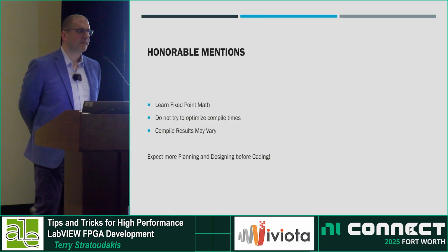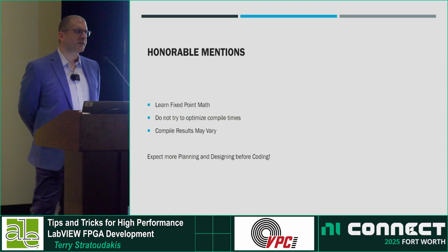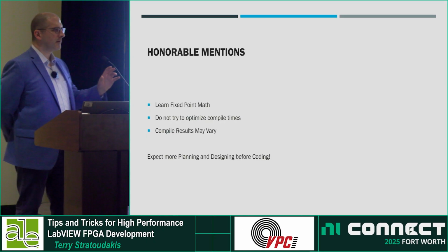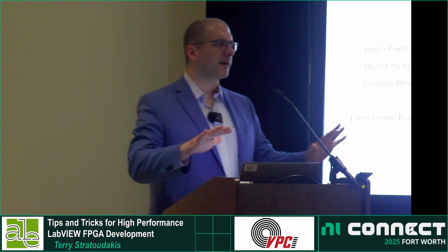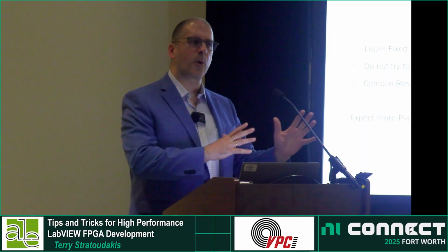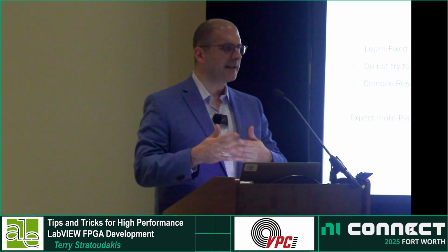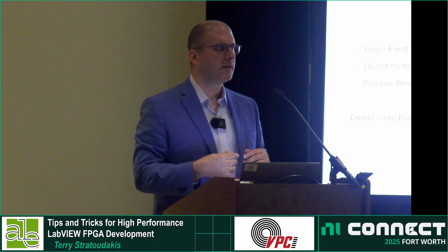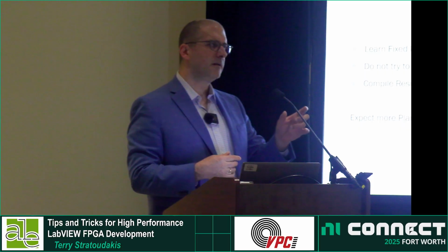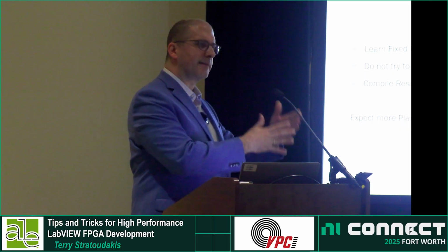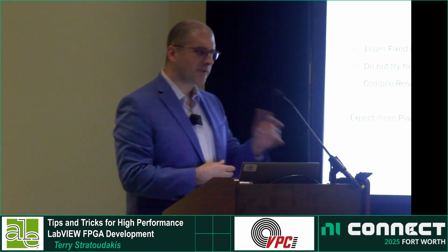Fixed point math. Why do we use fixed point math? So you've got integer math, you've got floating point math. The difference between integer and floating point math is an almost order of magnitude of logic usage and process and time, like cycles. Whereas fixed point math gives you the ability to have fractions, but at the rate and resource consumption of integer math.